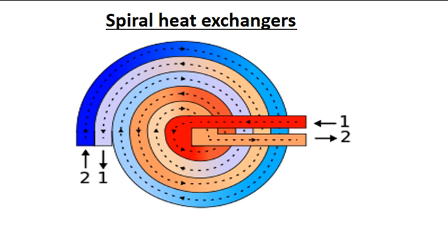This design is that of a condenser and is usually mounted vertically. It is designed to cater for the subcooling of both condensate and non-condensables. The coolant moves in a spiral and leaves via the top. Hot gases that enter leave as condensate via the bottom outlet.